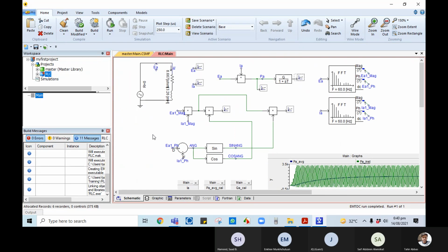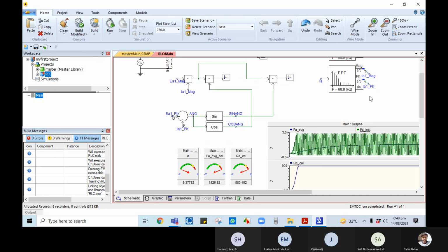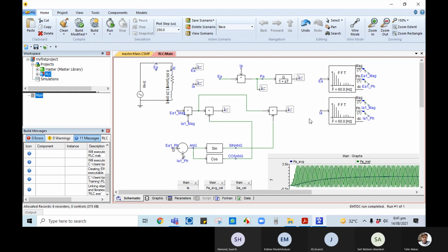We can make use of this information, the voltage and current, and then we can extract information using the calculations and formulations, but make sure that for the component you have placed, the correct input must be given. Like here the phase current is here using a data tab, so the same name must be here. Okay, so that will be considered as the input. If we change to a different name, this is a simple circuit, so it will take a wrong input and the case will not simulate, and in this way you will face an error in the simulation.